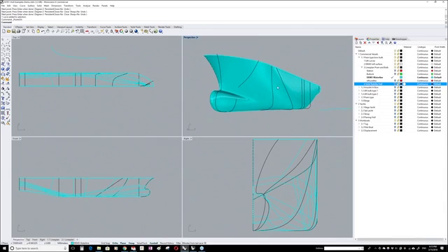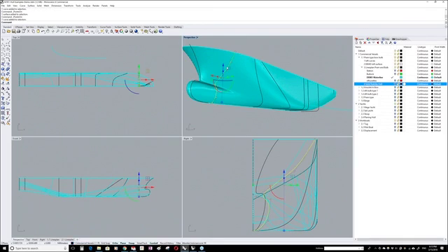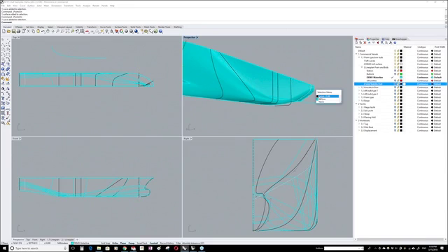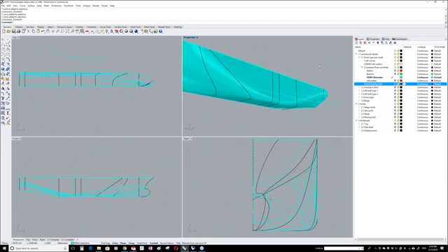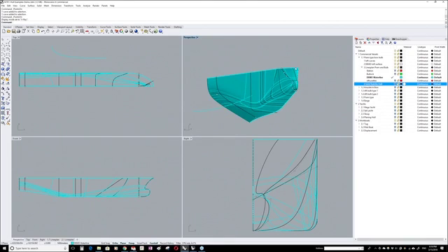So it takes some time. I saw that some of the people had used MaxSurf, and MaxSurf is using the control points of your surface. You can do that in Rhino as well. The disadvantage of this is that you always need a lot of control points. So if you need one curve with a lot of control points, all the other places have a lot of control points as well. While with the loft method, this curve can have a lot of control points because we need a lot of shape manipulation, but another curve can have fewer control points. I don't know if it's in this case. Yeah, here I think I put it on. I can better put it on maybe on X-ray. You see, this one has 3 control points, while this at the bow has a lot of control points, and that is really an advantage of the loose loft method.